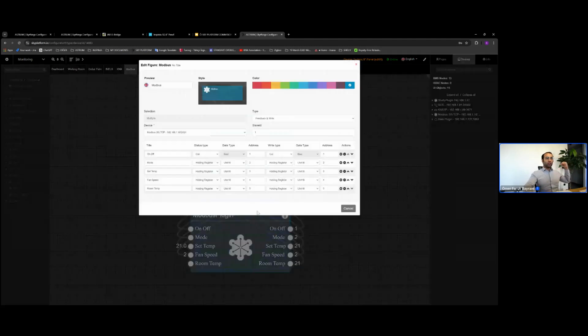So in the mini server, there is a slave plugin. Master here, slave in the mini server. This is my mini server's slave address, the mini server's IP address, and I have added a special port because I just want to control this one specific mini server device, for example. In that case, you can assign any port. As you can see, 1.16, 2424, it's for my Modbus TCP setup. I just added a random port.